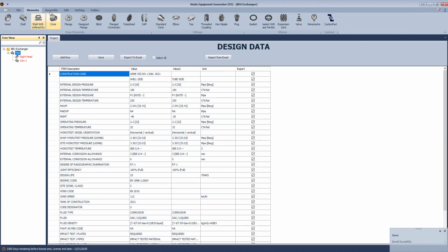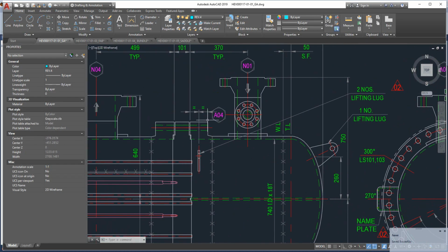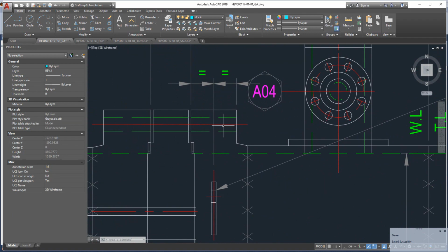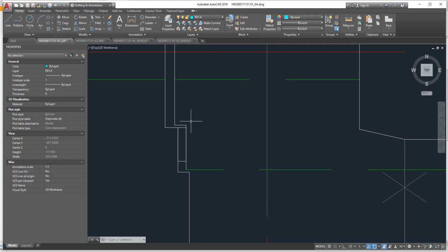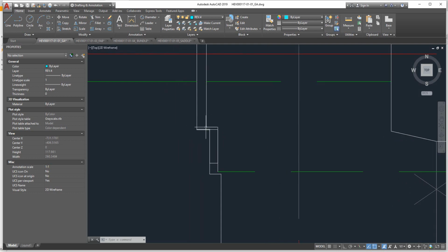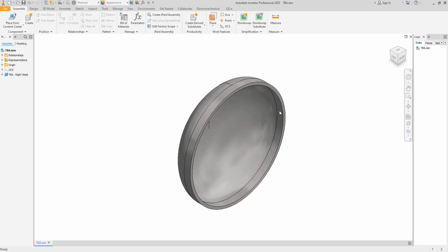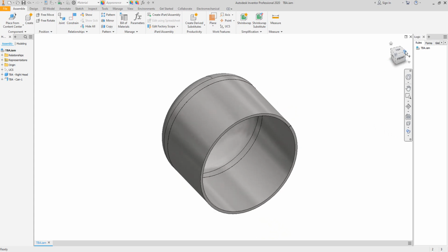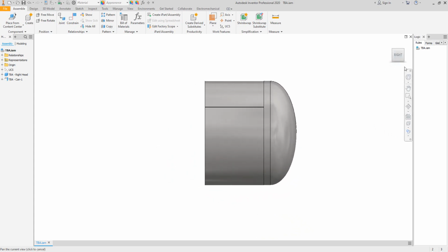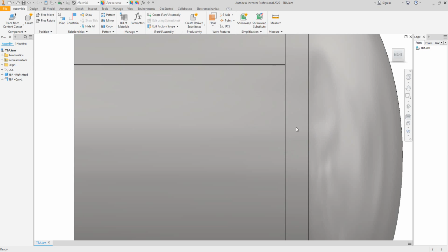Now we have another element. Let's start creating the assembly, and from here we have this flange, which is a heat exchanger flange with a grooved raised face. Okay, it's not with a projected raised face, it's a grooved raised face. Now let's open the SEG again, and as you can see here, we have the first bonnet. And in your drawing, you will use the right view to add the elevation view for this heat exchanger.